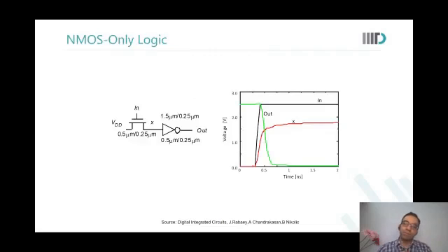Then what is the challenge? The challenge, so as we said, you put something and then at the output you put a buffer. The challenge is that now, let us say this in goes from 0 to 1. If in goes from 0 to 1, this NMOS turns on, it charges up Vx and output goes to 0. So you get the output as 0.